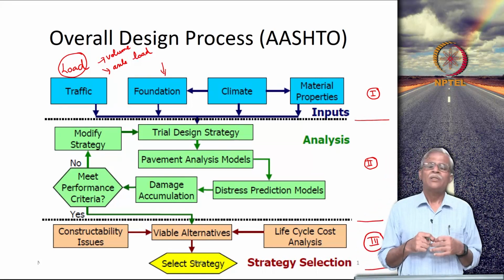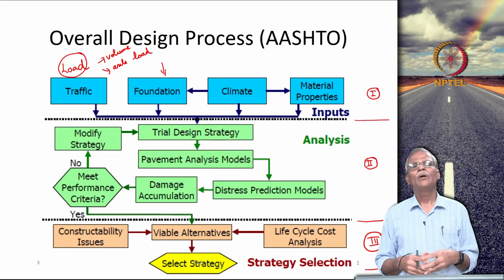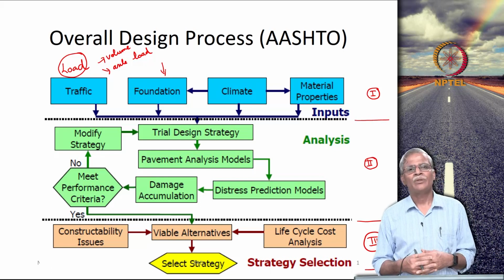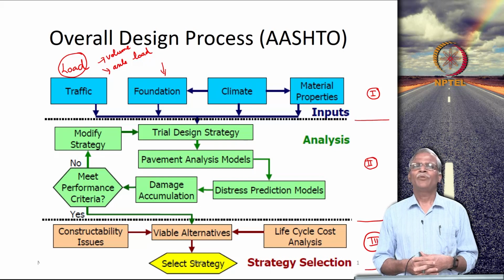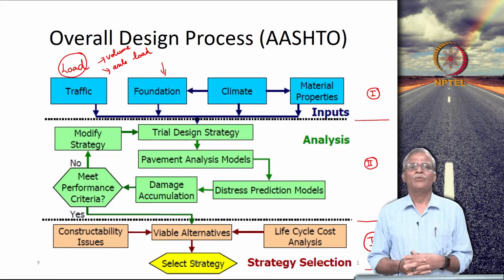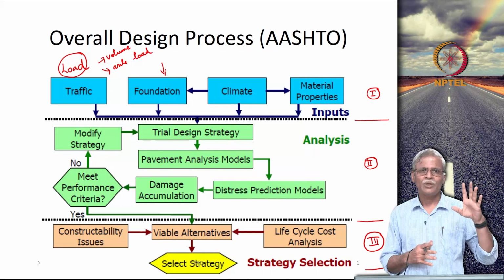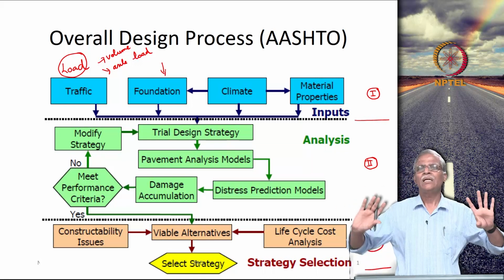So, when you are going to construct your bituminous pavement, depending on the country you live in, someone will say, go find out the CBR value of the subgrade, if it is going to be for bituminous pavement. If it is going to be for concrete pavement, they will tell you, go find out the modulus of subgrade reaction.